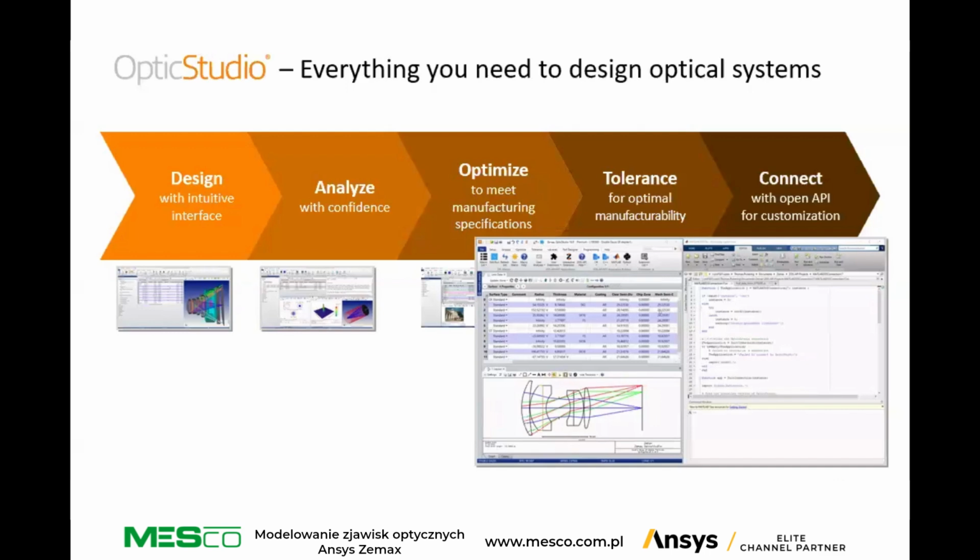There is also the Zemax programming language, which is an easy to learn programming language if you are not very familiar with this. And this allows you to write your own macros to automate repetitive processes. And you have also the option to build your own DLLs to create any surface, any object, source, or scattering function that are not shipped with OpticStudio.